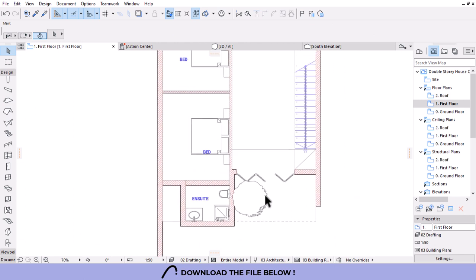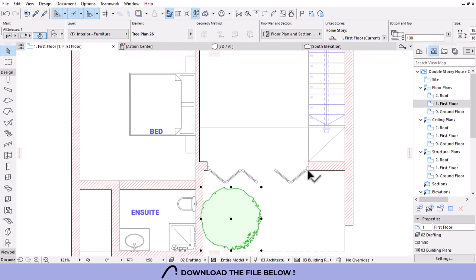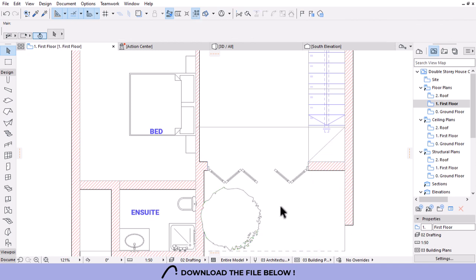Perfect. It's very important, guys, to understand the sizes of your doors. Door types are important. This one I would have to have in one size like that, so that when I do my door schedule, I don't have too many similar doors where the difference is only millimeters or 100. It doesn't make sense. So you have to group them in one ID or code with the same measurements. I think that will save your time, your life, and other people's life as well. Imagine someone who's manufacturing this door, especially if it's custom made doors. Yeah, it will take time. Especially these are just aluminum doors. Obviously, they are custom made, so think about that as well.